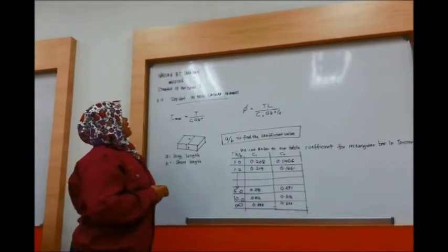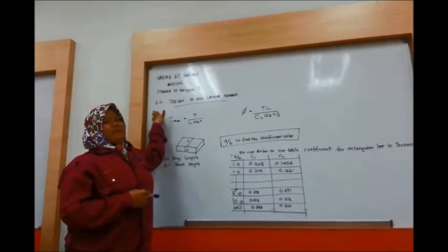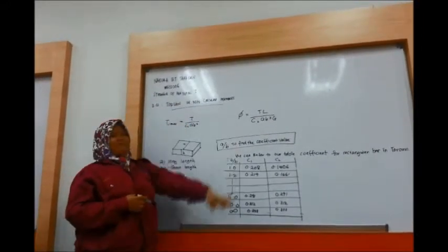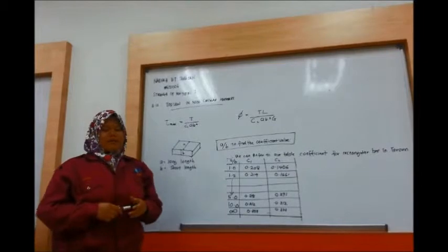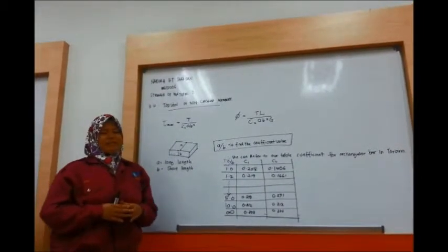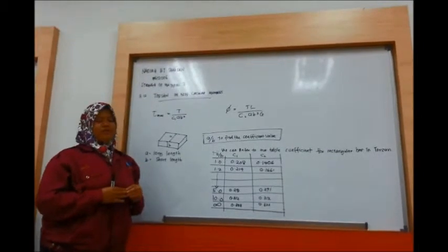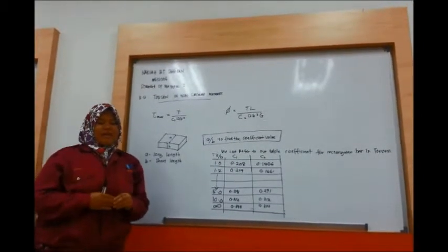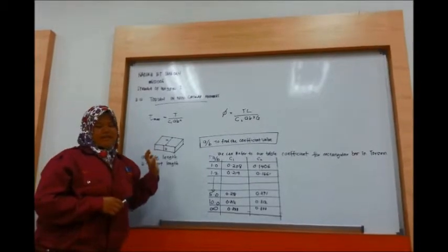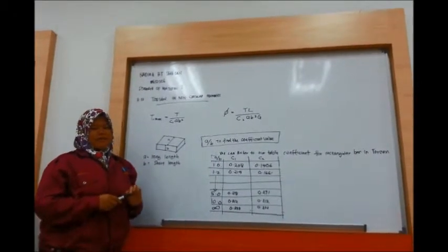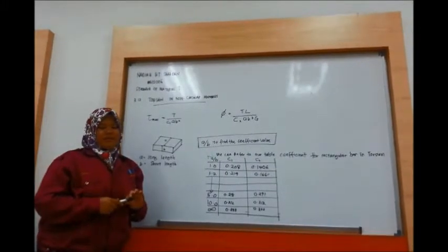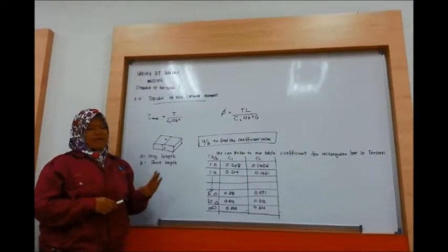MG12006. Okay, this is my subtopic that I will present in my project: torsion in non-circular members. Planar cross sections of a non-circular shaft do not remain planar, and stress and strain distribution do not vary linearly. For a uniform rectangular cross section, the maximum shearing stress occurs along the center line of the wider face of the bar, and likewise the angle of twist.